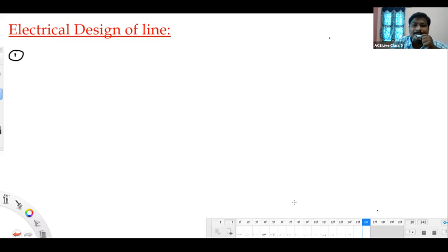Whenever you want to send more and more current, obviously we have to increase the size of the current flow path. So the area of cross section of the conductor you choose should depend on the current rating of the conductor, particularly the RMS current rating. So they are directly proportional. Conductor area of cross section is proportional to the current rating of the conductor.